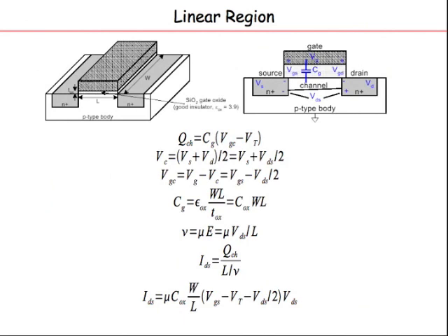Okay. So if you look out here, again we come back to the cross section. There is a capacitor out here, Cg, which is the gate capacitor. What is called the gate capacitor? There is a dielectric, it's an insulator, and you have a channel formed, and the channel is right at the surface. This cartoon representation seems to show there is a certain depth to the channel. But in reality the channel is pretty much at the surface. So it's like a 2D sheet, and you have the other plate of the capacitor. So you have pretty much a parallel plate capacitor Cg, which is between the gate and the channel.